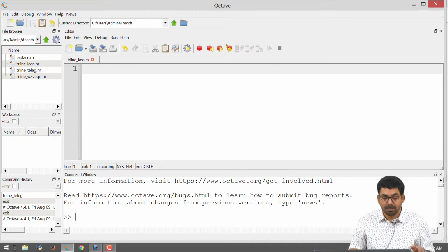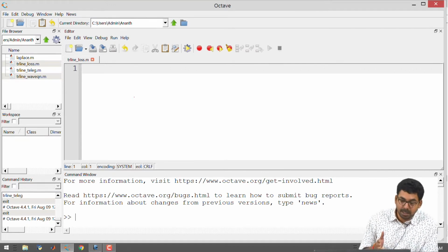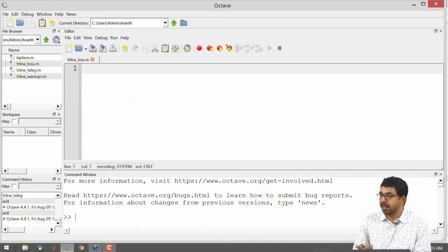So in this class, we are going to see the computational, programmatic version of whatever we saw for the AC excitation of the transmission line, and also include the losses, that is R and G, into the model. And we have derived some partial differential equations that we are going to plug into the program and actually see what can happen, to understand the exponential decay or exponential growth corresponding to your attenuation constant, whether it is positive or negative. This is the objective.